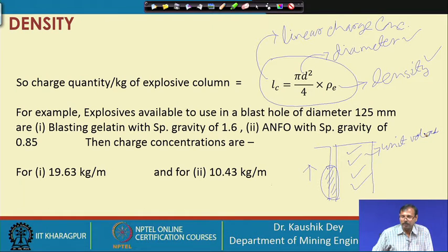So, if we are using more dense explosive material, then our charge concentration is more and our unit volume per charge requirement is also becoming more. So, basically the charge concentration requirement depends on the strength of this rock mass.